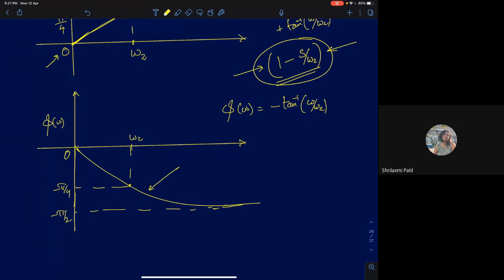Okay, so generally when you add zeros in the system, we said zeros don't determine stability of a system. That's true for open loop systems. If you talk about an open loop system with zeros, you can say that really doesn't affect the stability of a system at all. But the moment you put the system in feedback, zeros will have a significant effect on the stability of a system. Whether they can make the system stable or they can make the system completely unstable as well. And that information we will gather from the phase response. That's where phase response will come in very handy to get an idea about how close to instability we are.